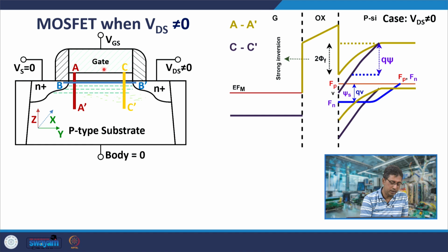If we look at the current density of holes, we know that it is proportional to the hole concentration locally, and its product with the rate of change of hole quasi-Fermi level along the direction in which you are looking at the current density. So, along the z direction, it is given as shown here.